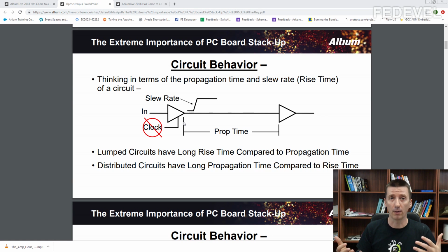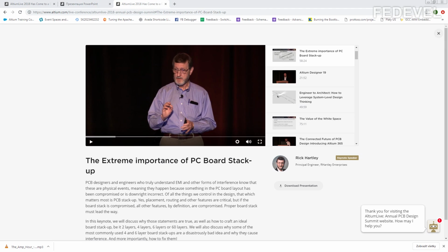You still may see problems like random interrupts, or your board may reset randomly because there is crosstalk between your reset signal and some other signals. Your microcontroller board doesn't have to run on high frequency, but it is using sharp edges. The changes on the signals are happening very quickly.